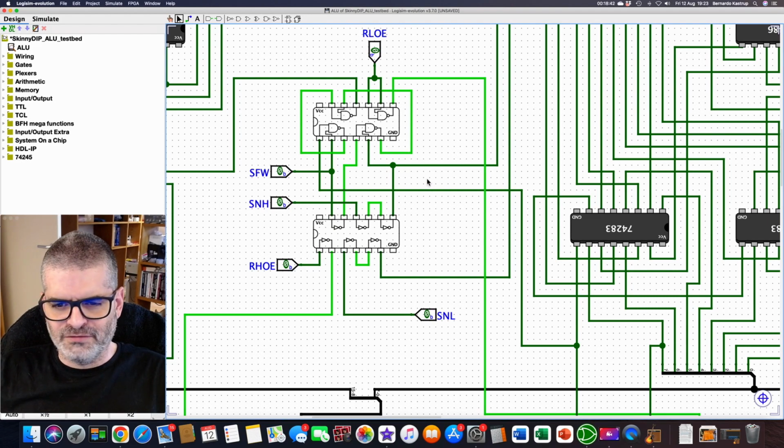I mean, this is very simple stuff. You will not get a lot more important stuff from him either. But this is just a simple example. Considerations of fan out, considerations of EMI and reflections when a trace will branch out in several places, and what do you do to counter that? And when do you choose a chip with Schmitt trigger and one without, even though the chips are otherwise identical, and many other things? What is the maximum current that can be sourced per pin, and then you cannot just add up that current for all the pins, because the total that the chip can sink into the ground pin has another value, which is less than the sum total of the currents that each pin can source.